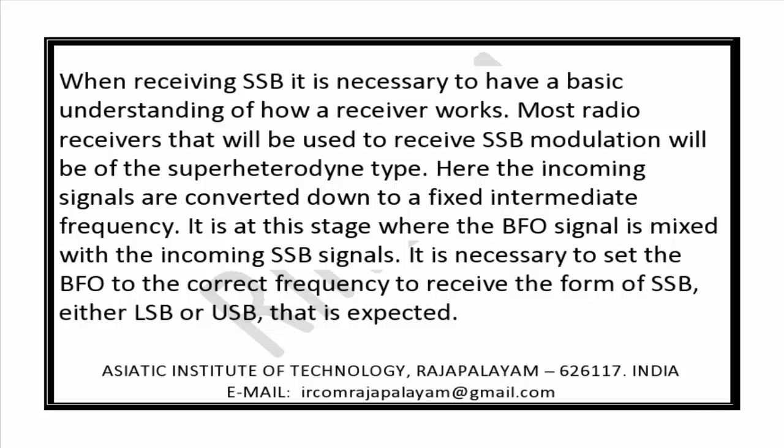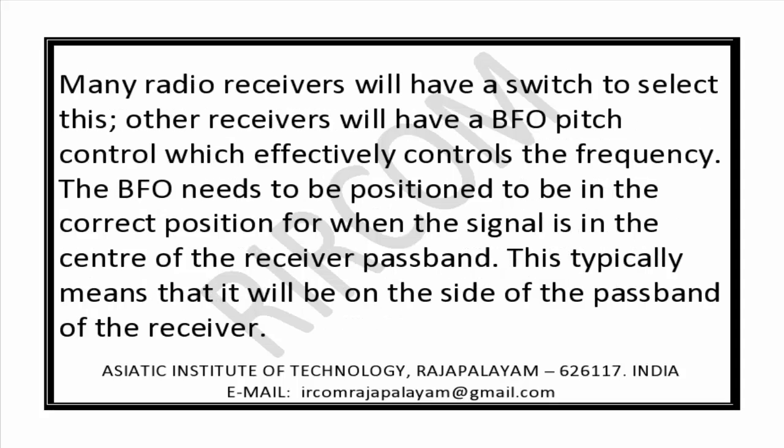It is necessary to set the BFO to the correct frequency to receive the form of SSB, either LSB or USB, that is expected. LSB is lower sideband, USB is upper sideband. Many radio receivers will have a switch to select this. Other receivers will have a BFO pitch control which effectively controls the frequency.